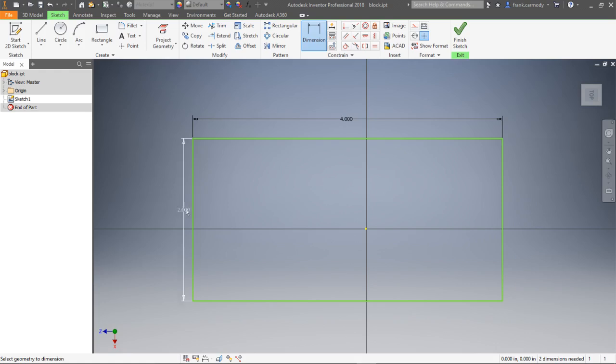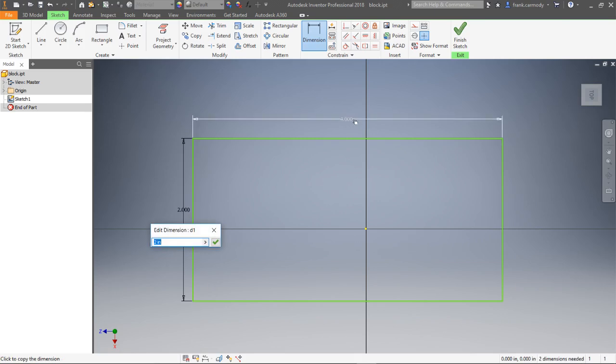The other thing we can do with dimensions is this. We can use dimensions, we can actually just use math to dimension them, right? Okay, so let's say that I always want the height to be half the width. I can click on the dimension, I can click on another dimension, so now it's D0, right? That's like a variable referencing the other dimension. And I can go divided by 2 and hit enter.